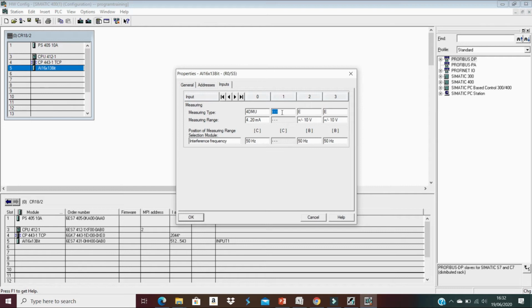To avoid this, normally in the initial stage itself we can configure all the ports, even the spare ports, with whichever input you want. It is for safety purposes.